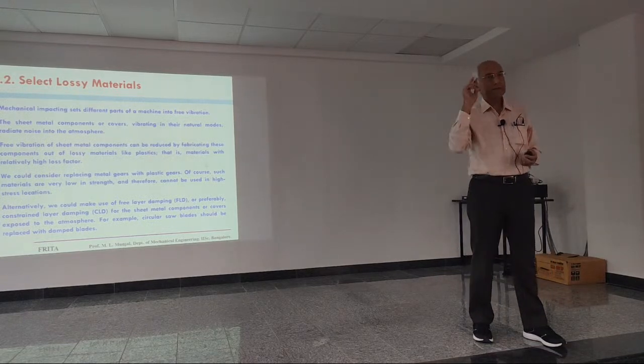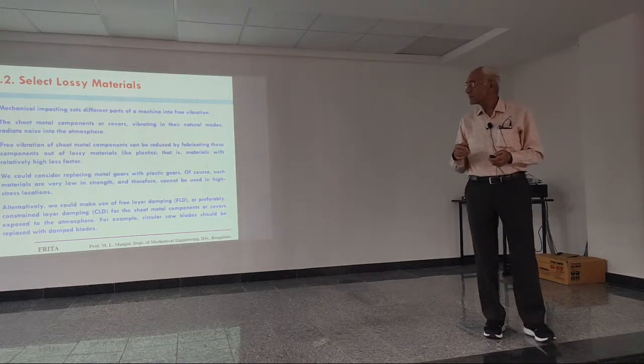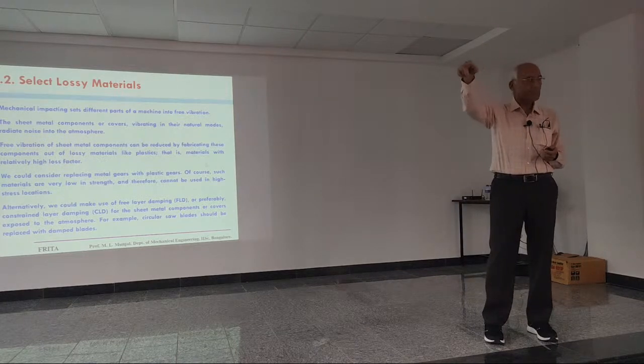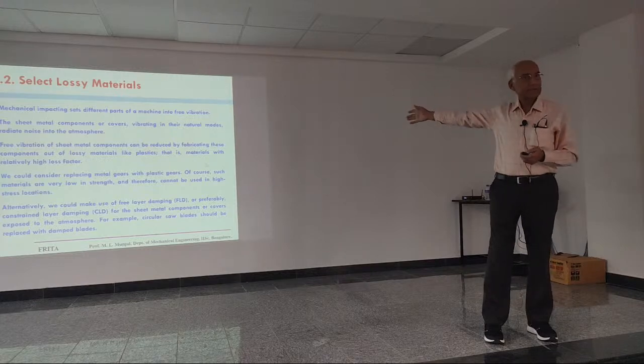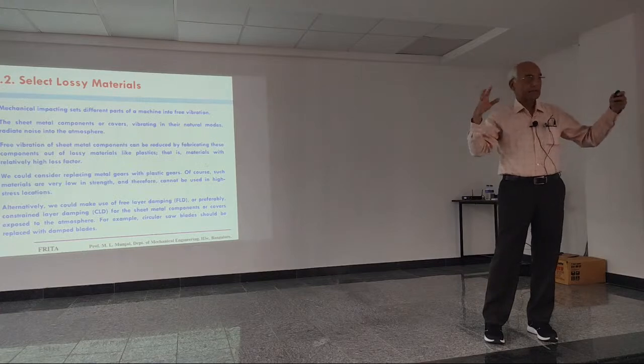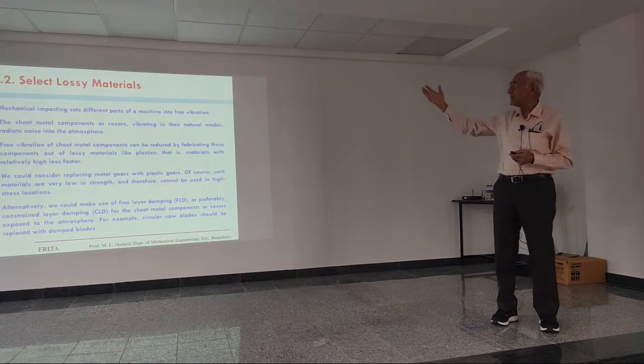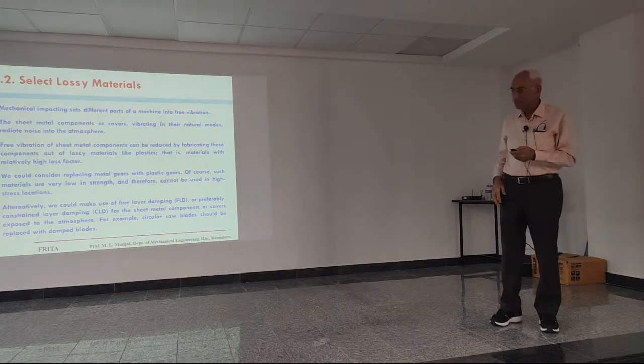Okay, so it's a very interesting thing, and therefore all we need to do is make sure that the final noise, where it is coming from, those are always this kind of covers, sheet metal components, and they act like mechanical loudspeakers. So if we have built in sufficient damping, we will have no problem.